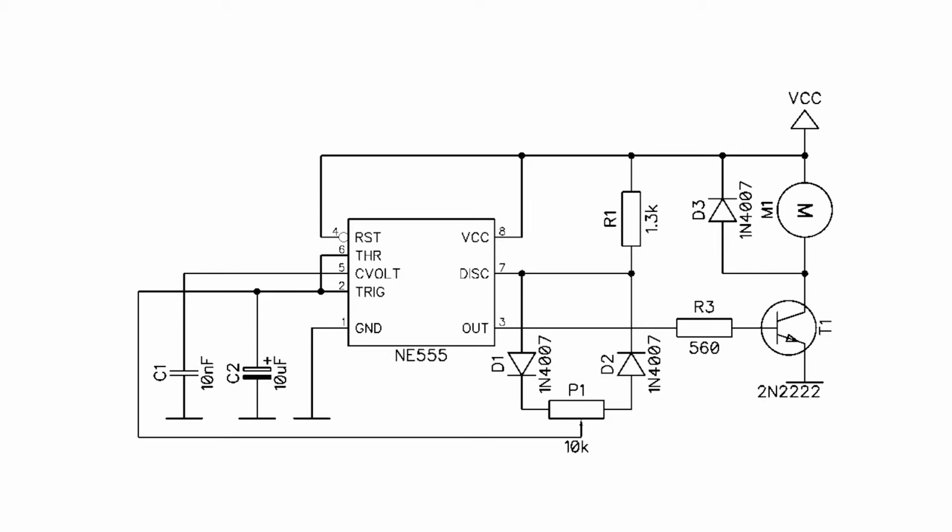When the capacitor is charging, the current flows through R1, D1 and the left part of P1. When discharging, it flows through the right part of P1, D2 and the discharge transistor contained in NE555. If we add in series with D2 an additional resistor of a value, for instance R1, we would get about 50% of the fill in the middle position of the potentiometer.